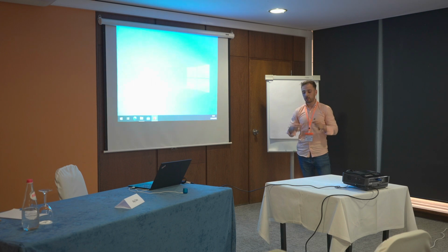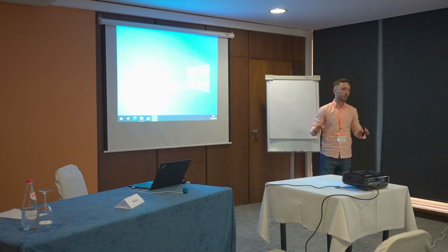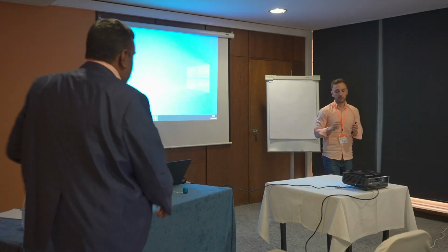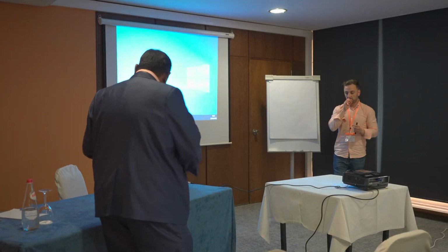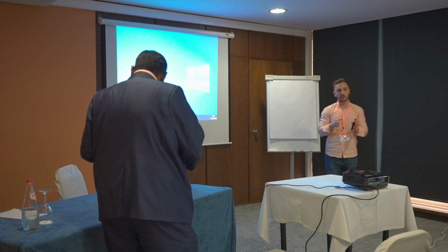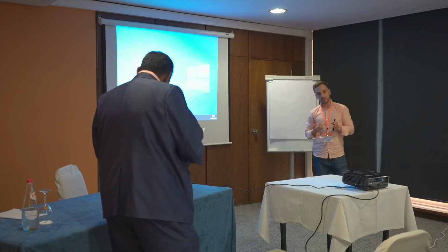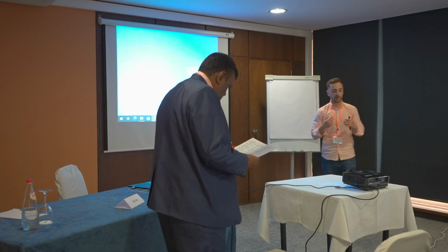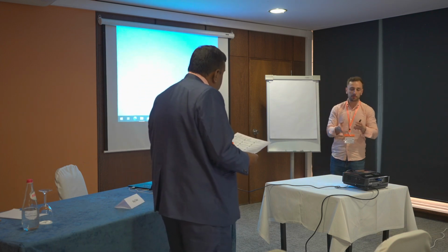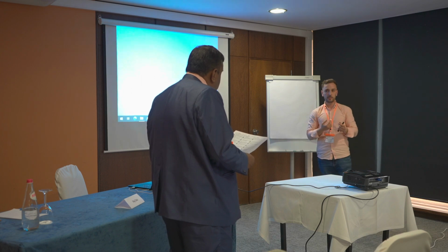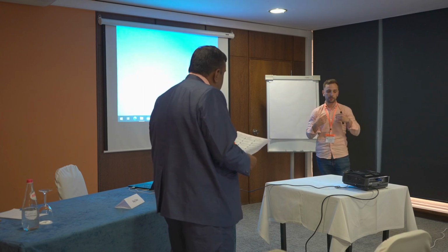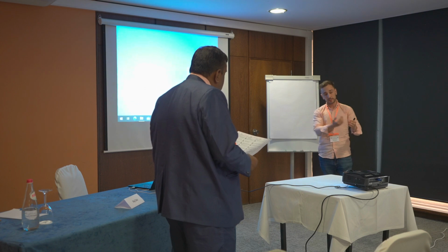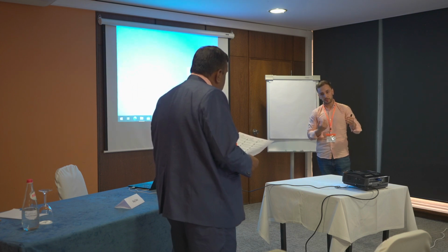No, we just sit the mannequin in the driving position without a seatbelt. I forgot something important to mention: the seat must be in the most retracted position. If we have an accident, the seat sometimes retracts. So the mannequin should be introduced in the retracted position of the seat.